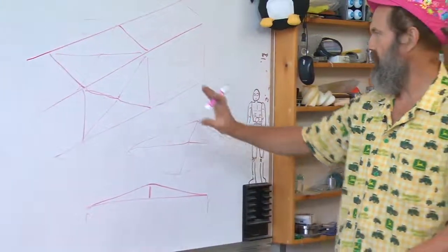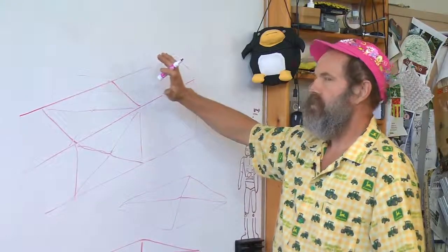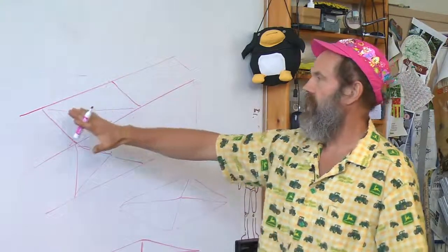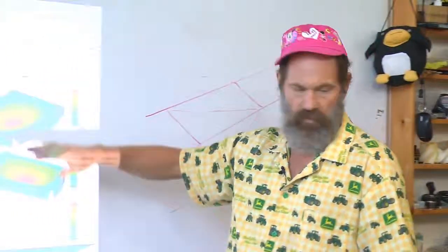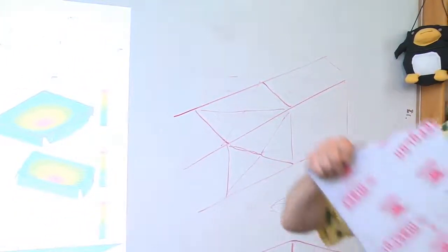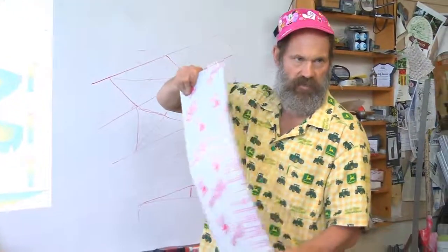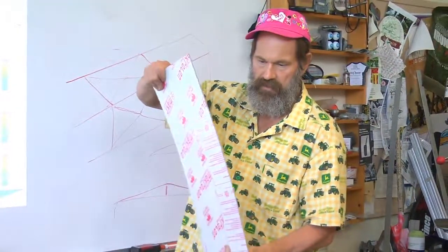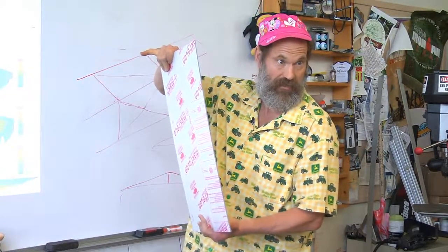But that's enough to make these plates stable so they're not a taut diaphragm, because a taut diaphragm will oscillate between the two modes, this mode shape and this mode shape, because it's neutrally stable. Remember, we're going back to that stability discussion.